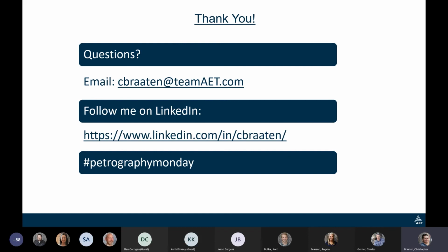And then looks like there's a follow-up question from Adrian. Does the use of fly ash in aggregate have toxicity concerns? No, not that I'm aware of. It's used in concrete, so to clarify, when used in concrete, it kind of gets bound up and locked in that concrete. So it shouldn't cause any concerns when the structure is demolished, and that concrete is typically reused as recycled aggregate. So as far as I know, I don't think there's any toxicity concerns that I'm aware of.